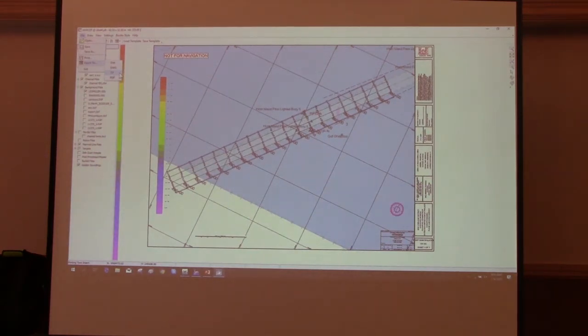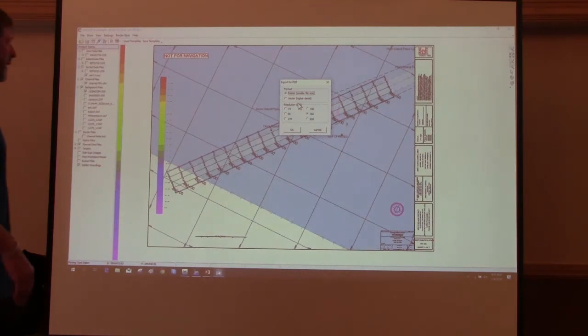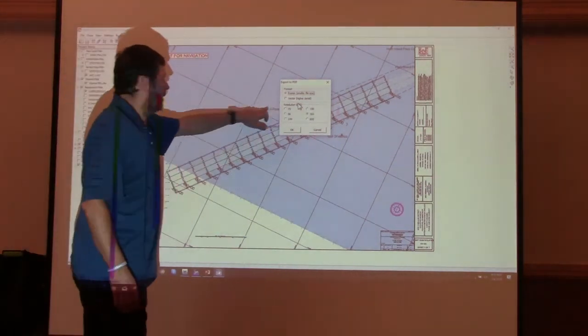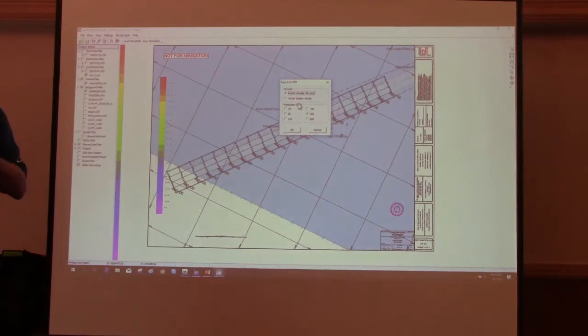But I think most people prefer to plot either to a TIFF file or to a PDF file. So let's do a PDF real quick here. And again, you have some options here, whether you want to do raster, which is a smaller file size, or vector. The vector is higher detail, and what's nice about the vector is it does create the different layers. So if you're sending it to somebody, they can actually enable or disable the layers in the PDF file.